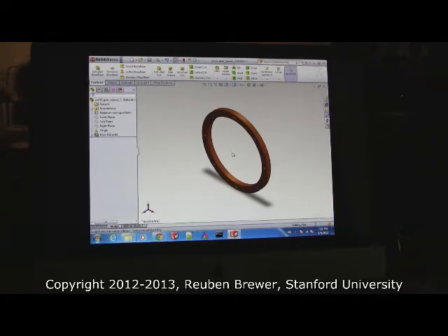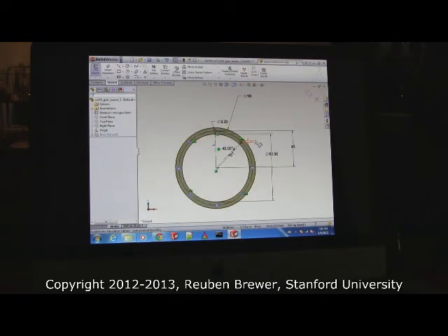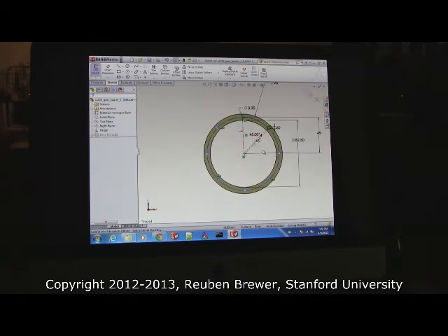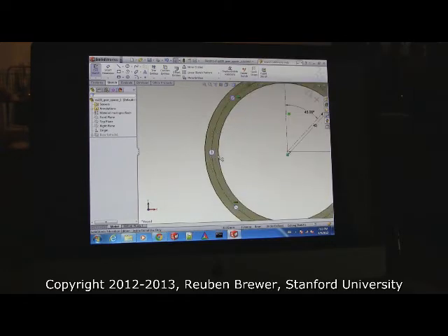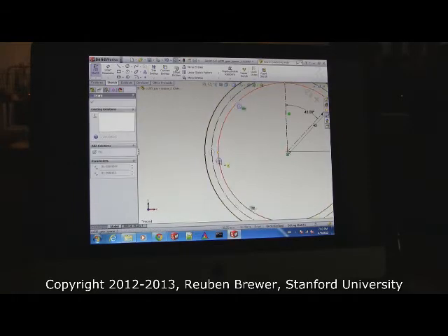So we're good. So now that we know that, remember we left the sketch a little crazy. So go ahead and edit the sketch, and then select the normal face so that we're back in it looks normal. Now I want you to take one of the blue circles, click on the diameter of a blue circle, not the diameter, okay, click on the middle of one of the circles. Watch my screen, see that?